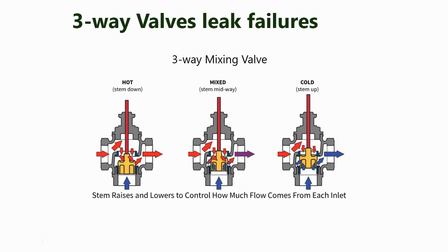Nevertheless, with either type, three-way valves are much harder to diagnose since they're always flowing water through them anytime the pumps are running. So ultrasonic won't tell you if it's leaking by because it's always going to be noisy. And we saw a couple slides back, trying to diagnose leakage across a valve body using infrared just doesn't work very well either. So for diagnosing three-way valves, it's best to measure for leakage right at the heating or cooling coils that are being controlled, and then overriding the valve shut and measuring for any residual heat that still may be entering the coil.